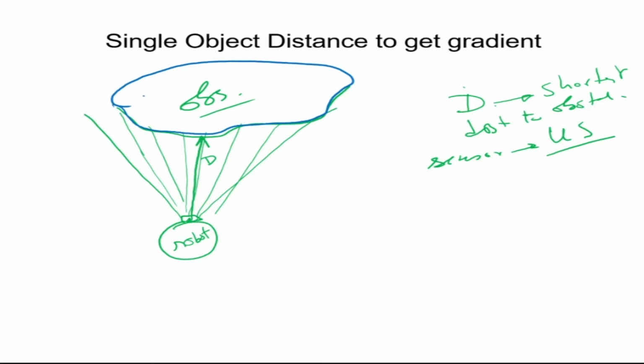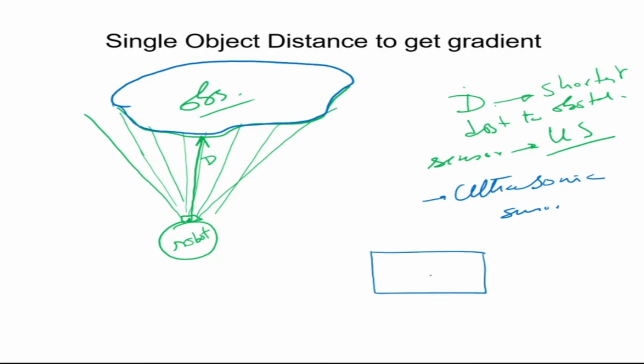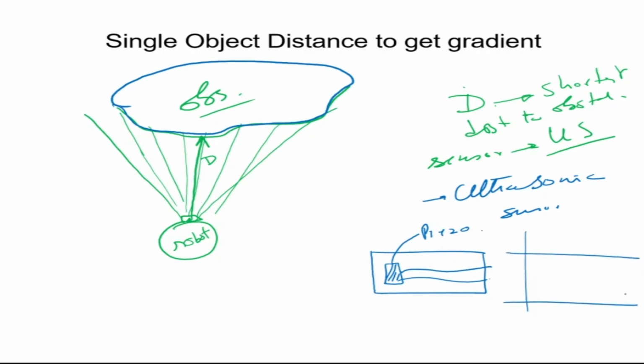Now a real robot would have sensors, like ultrasonic sensors. So these ultrasonic sensors can find distance, and as you would be familiar with ultrasonic sensors, how it basically works is that there is a ceramic transducer here, okay, and this is a piezo crystal, and the piezo crystal is actuated in a particular frequency. So in a particular frequency we give it actuation signals.